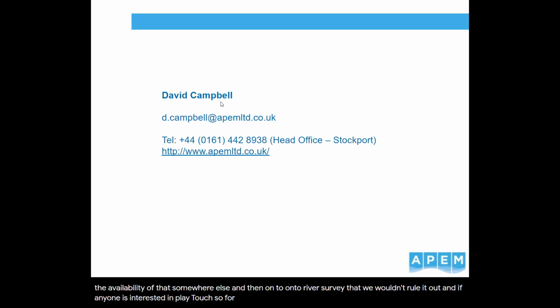So from Gemma, how close to the time of the aerial surveys do the calibration data need to be collected? For the grain size, that's derived from the imagery itself, so that could be done at any time. From the depth side of things, that needs to be pretty close, ideally on the same day of the survey.